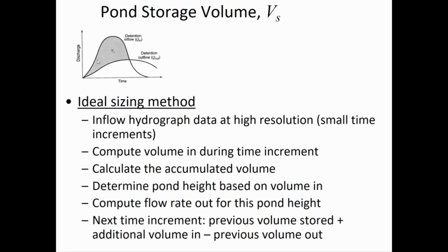So ideally what we'll have is an inflow hydrograph at high resolution, at least hourly increments. And the more frequently, the better, because what we're doing is kind of a numerical integration. We'll calculate the volume into the pond during some time increment.